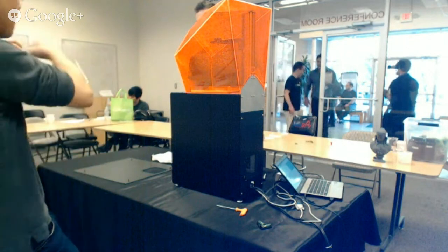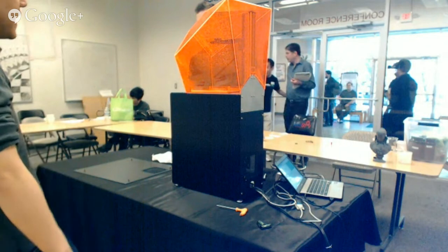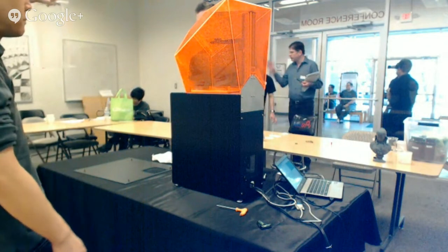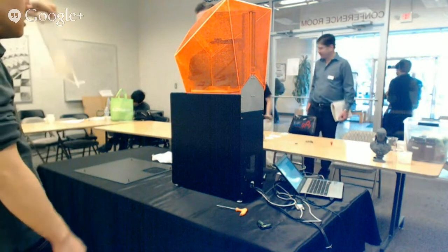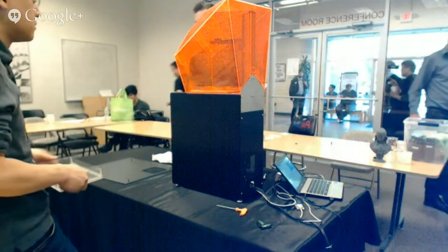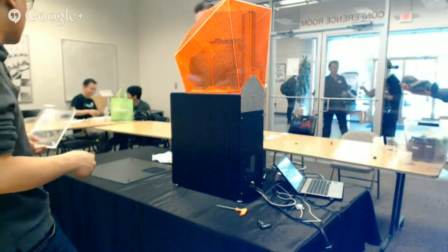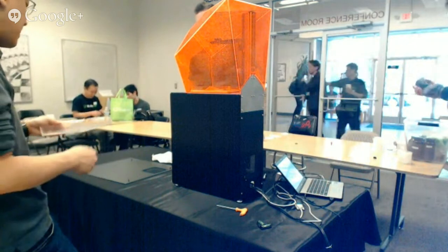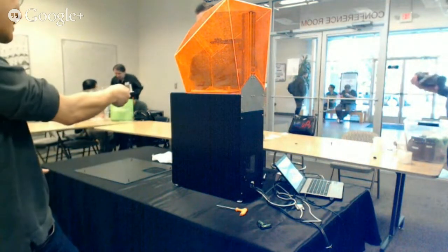If you are printing on bare silicone, then you consume the vat faster. Any extra exposure that you don't need will cause the silicone to cloud faster. I mean, that's a chemical reaction. Can you buy those, these vats? Yeah, you can buy them from your site. I mean, they're designed to be held on a specific way. You're going to have a hard time holding this onto something that doesn't use a flex lifting system because you only hold on this side.